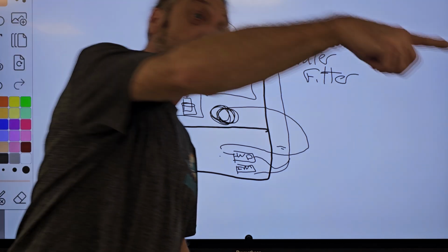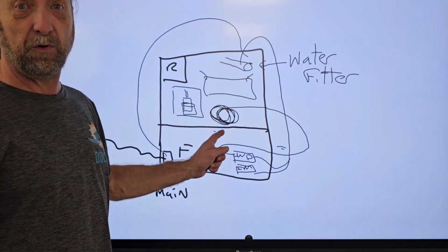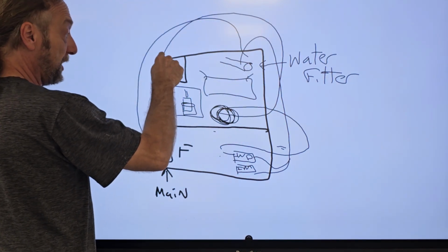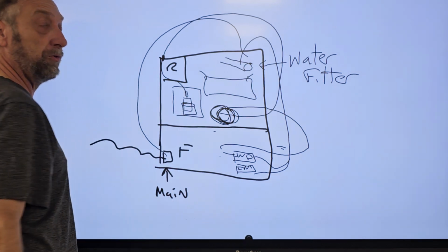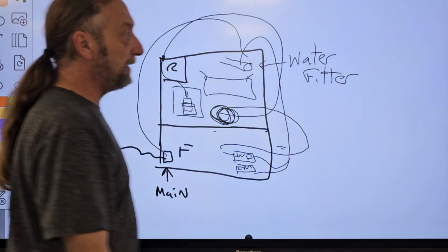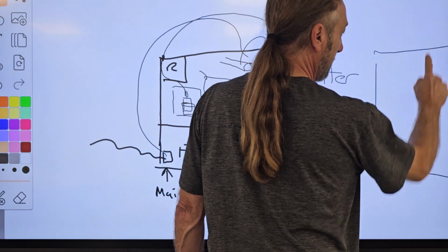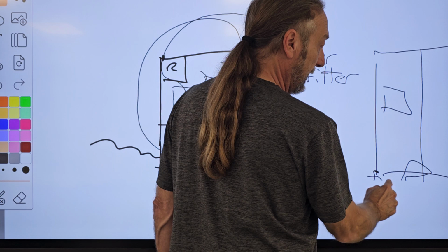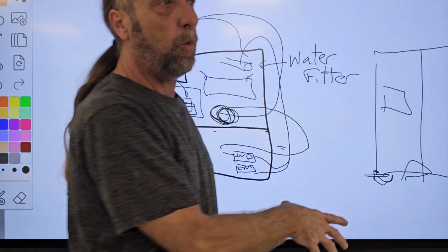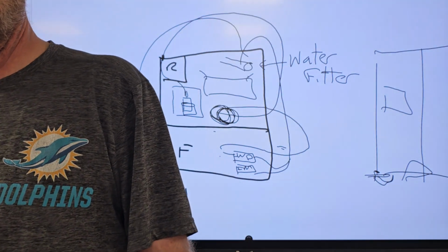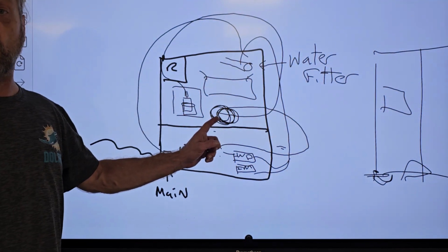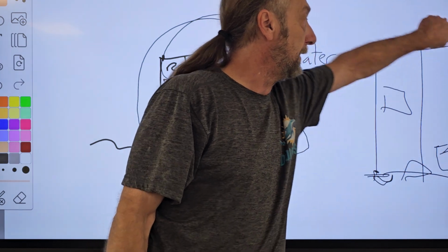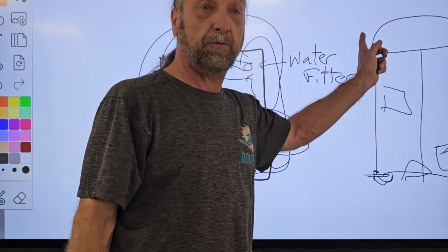We got to run back out of the refrigerator. We came in the fridge. We got to go back out the refrigerator and go through the upper hinge here, and inside the door is a hose. Now, on a side-by-side refrigerator, your dispenser's here and all your valves are down here. Your compressor's down here, and any hoses running down here are going to get warm from the condenser and the compressor. So even though this is chilled water, the hose between the tank and the refrigerator and coming out here is running underneath here before it goes up there.